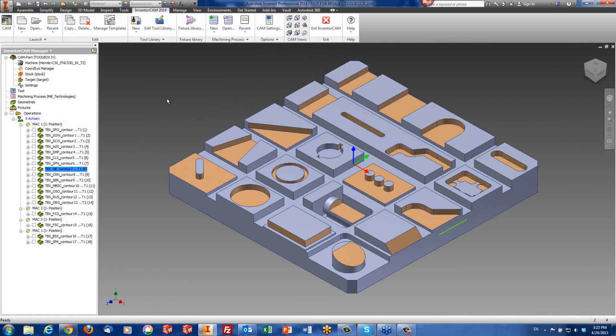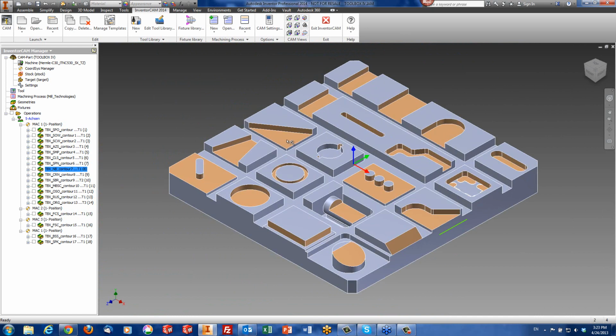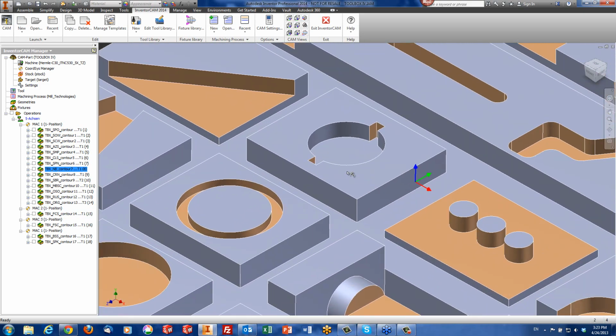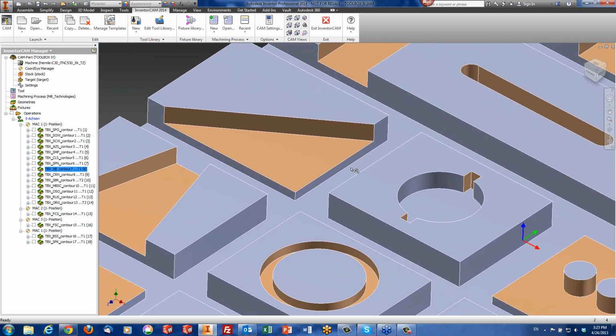I want to talk actually now about the next operation called corners. Normally when you do an operation over here, say using a profile operation, you choose this as your geometry and give it a clear offset. Now, with a clear offset, it gives you a lot of wasted moves because it goes in areas where it does not really have to work, because it goes according to the length of that line.